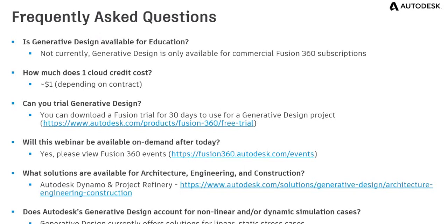So the first question from Kevin, when we were setting up the GE bracket, why did we clone the load cases rather than just adding separate force constraints to one load case? The reason that we've cloned them into multiple load cases is so that all of those forces would not be combined into one sort of ultimate force. In that case, we knew that this bracket had to be able to hold, in one case, 8,000 pounds in the positive Z. But then in a different case, it also needed to hold negative 8,500 in the Y. So if we combine those within one load case, we're going to have one separate load where we really need to account for two. And that's what the ability of multiple load cases allows us to do.